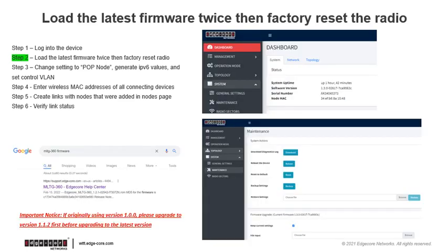All right, next thing to do is, of course, load the latest firmware, 1.3 currently. The thing is with the DN, you have to do an intermediate step with 1.1.2. It won't let you load, say, 1.0 or older firmware than 1.1 or so with the 1.3 or later firmware. It has to do with the file size issue. The original firmware wasn't set up to handle a larger file size that the newer firmware is. So it's just another step.